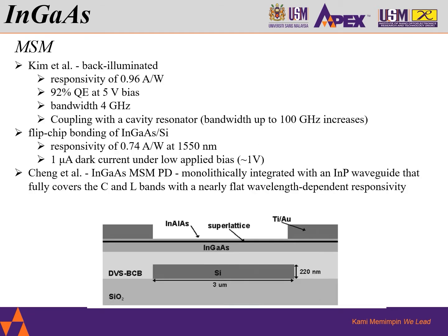A researcher introduced a back-illuminated indium gallium arsenide MSM-PD with a record responsivity of 0.96 A/W and a 92% QE at 5 V bias, but only 4 GHz of bandwidth. However, coupling with a cavity resonator can increase the bandwidth up to 100 GHz.